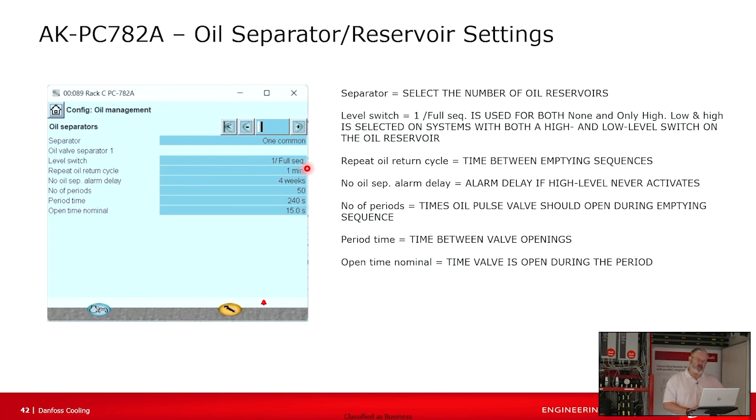And then I'm going to wait 1 minute. I'm going to do that again. And I'm just going to do that forever because remember, we physically wired in a jumper. So every 5 minutes, I'm going to open the dump solenoid for 15 seconds. And I just do that forever. That's a pretty effective means.